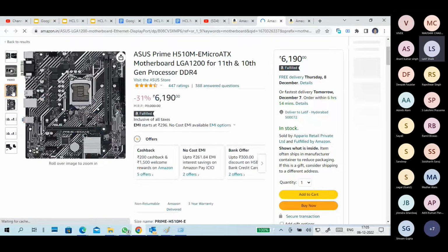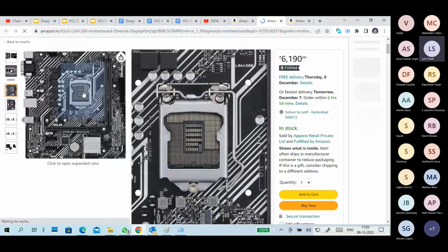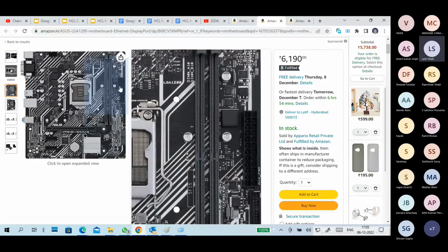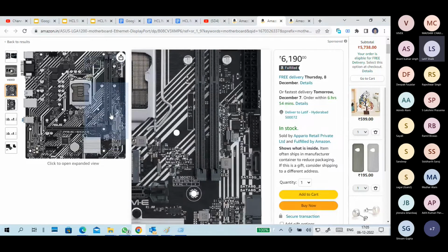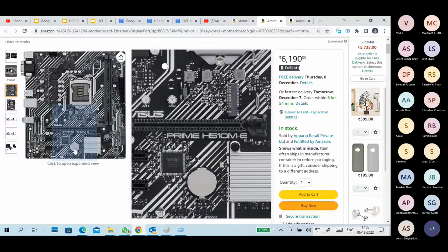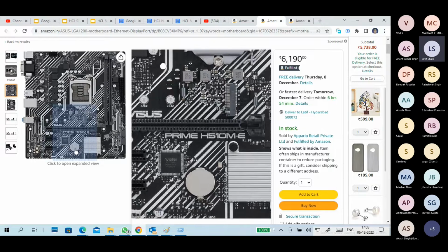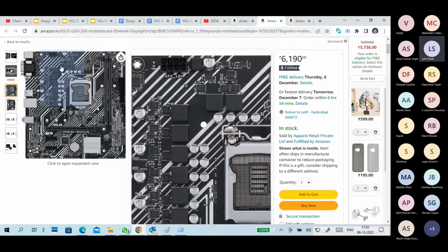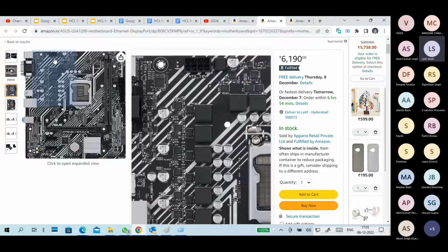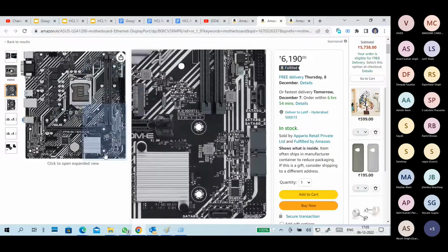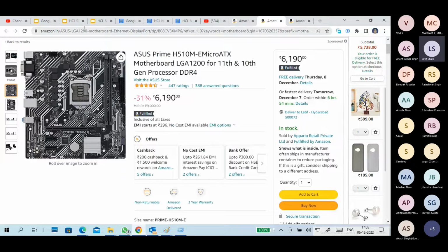Let's have a closer look at recent motherboards. This is the processor slot, and this is a RAM slot. This corner one is your power supply connection, SMPS, graphic card, PCIe slots. This is the BIOS chip. This is your BIOS battery. These are other chipsets. This is 8 pin from SMPS to the motherboard, 12 volts for your CPU. So those are the basic things.